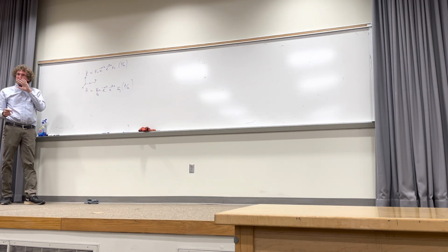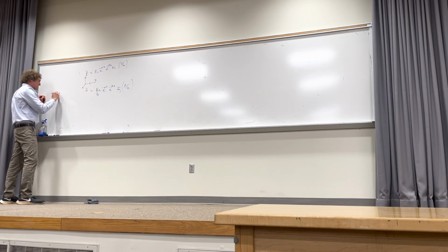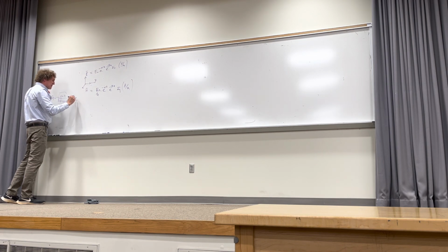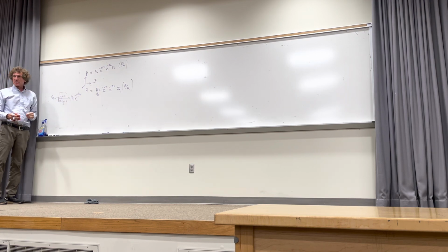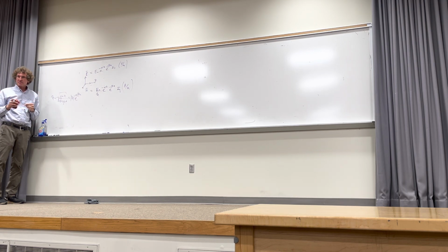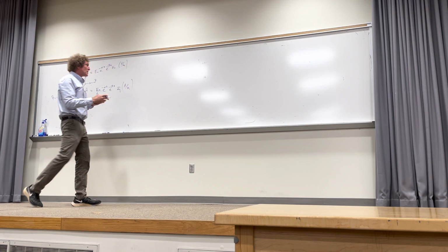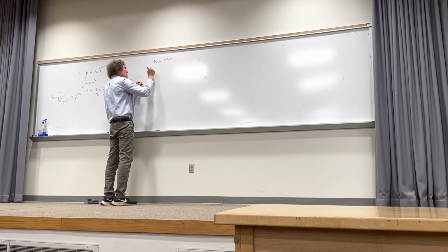Okay, now I'm going to add a little something to this. Because eta, in general, is equal to the square root of j omega mu over sigma plus j omega epsilon. Eta has some magnitude, and it is at some angle. Now, I'm showing you, this would be the general form, right? But we know it can be complex, so it would have a magnitude of eta, and it would also be at some angle, because it's complex. Y'all follow me? Possibly complex. Y'all agree with that? All right. Now we get into power flow. When we talk about power flow, we really talk about power density.